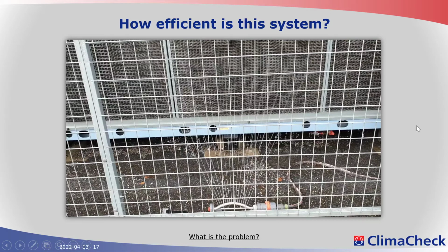This is going to put a lot of fouling on your condenser, so it's quickly going to deteriorate, but it also costs a fortune in water consumption. So not a good solution. Fix the problem instead.